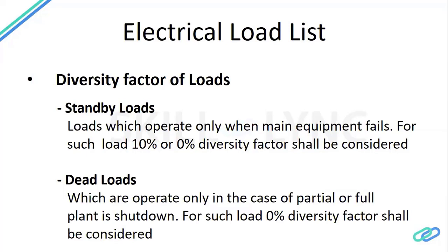Fourth is dead loads. These are loads which operate only in the case of partial or full plant shutdown. For such loads, you don't need to consider them in the electrical load list. You will list them for the feeder purpose, but you will not consider them in the load list. For example, welding sockets and fire pumps are dead loads.